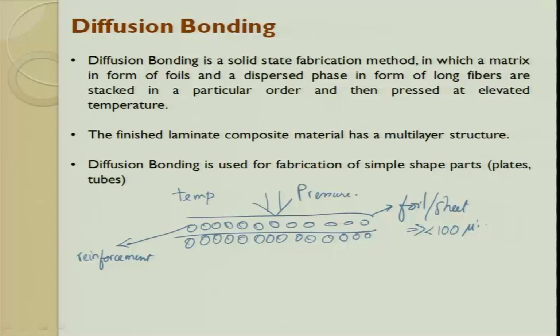consolidation. In order to have a proper consolidation, you go back and remember the wettability property. If you want that wetting property, then you try to melt this fellow to some extent, and then it tries to take a shape. So, temperature and pressure both are applied in a die or directly on a component. Generally they do not apply it directly, but in a die, and the die gives the shape of the metal matrix composite, whatever you want.